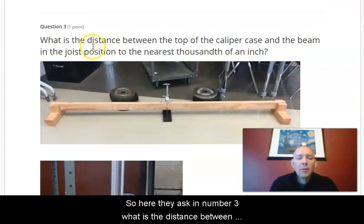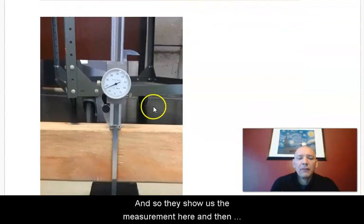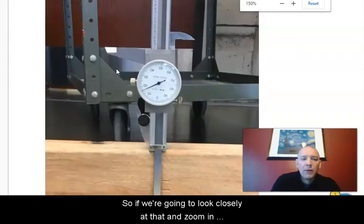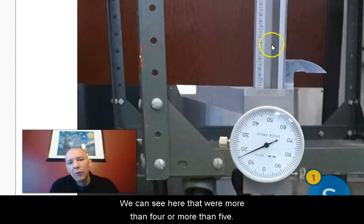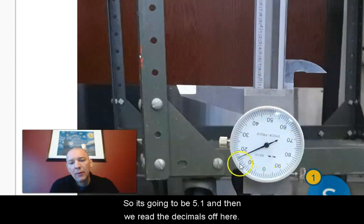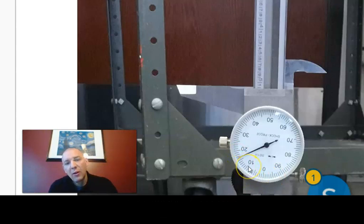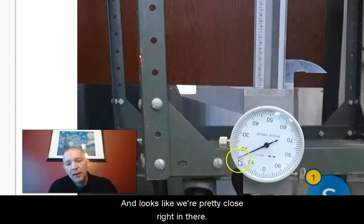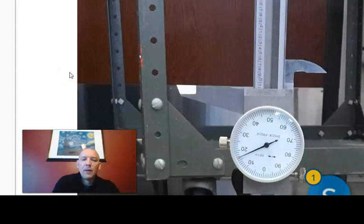So here they ask, number 3, what is the distance between the top of the caliper case and the beam? And so they show us the measurement here, and then they zoom in onto the caliper. So if we're going to look closely at that and zoom in, we need to read this off. So we can see here that we're more than 4, we're more than 5, we're past the 1, so it's going to be 5.1, and then we read the decimals off here. And you'll have to look closely and see which one this is closest to. So here's 5.110, here's 5.120, and it looks like we're pretty close right in there. So you'll practice reading that off and putting your answers in.